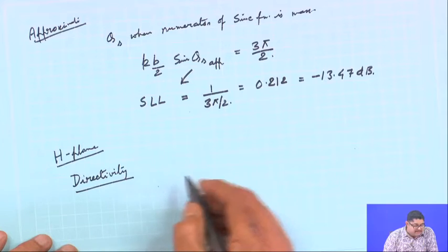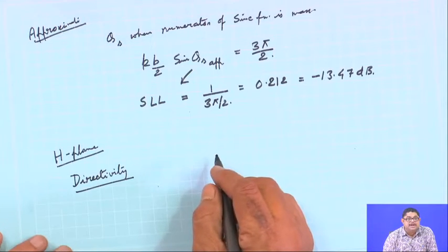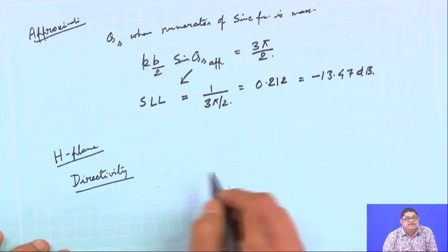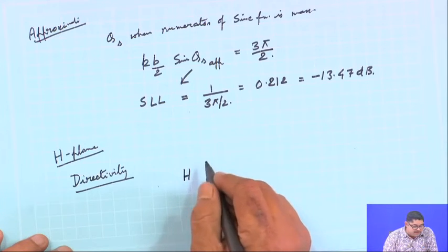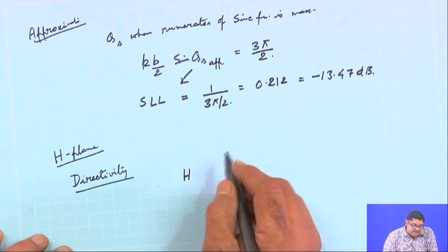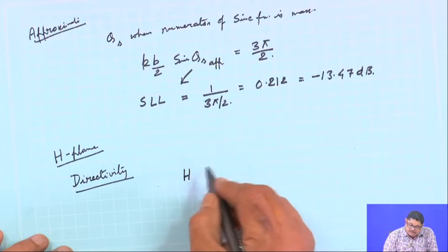So, we can say that total power radiated, instead of calculating from the far fields, we can also calculate from the aperture fields, because whatever aperture is sending, so that is an easier way, because it is a uniform field. So, that is why for PR calculation, total power radiated, we will take the help of the aperture field. So, we know what the aperture field is.